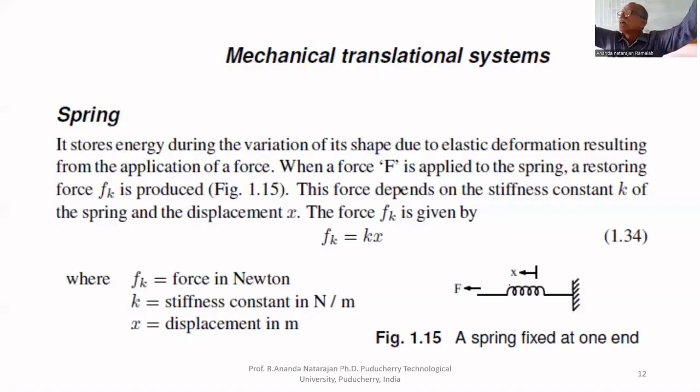One rod is there. One end is fixed, and you pull the other end down and leave it. What will happen? It has the spring effect, and it either goes slowly to that point, or it oscillates and finally settles. That effect is called the dashpot effect, along with the spring effect. So any mechanical system, if you model it, has the property of mass, the property of spring, and the property of dashpot.